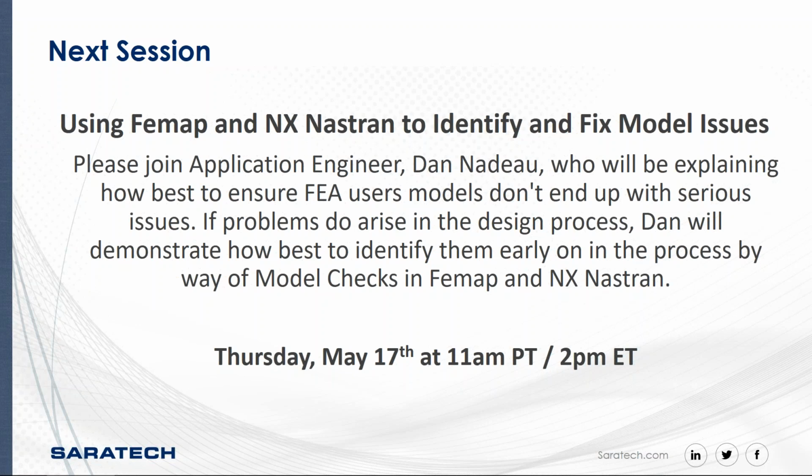Let's see. So it sounds like that. You do have options in your properties. If it was a glued contact, there's a glue factor. By default, it's actually 1. So that's something you could play with if you don't have full bond on the entire surface. You could play with that glue factor, bumping down from 1. Or with the advanced nonlinear solutions, there's some additional settings there, and that's something we can talk about offline. So please reach out to us if you'd like.